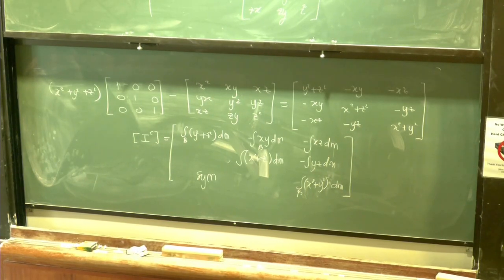These are called the mass moments of inertia because they measure mass distribution. If you've taken mechanics of materials, then maybe you've seen area moments of inertia. Have you seen those? Instead of dm, you're going to have dA, the distribution of the area, looking at the geometry of the problem. The mass moments of inertia look at the distribution of the mass.